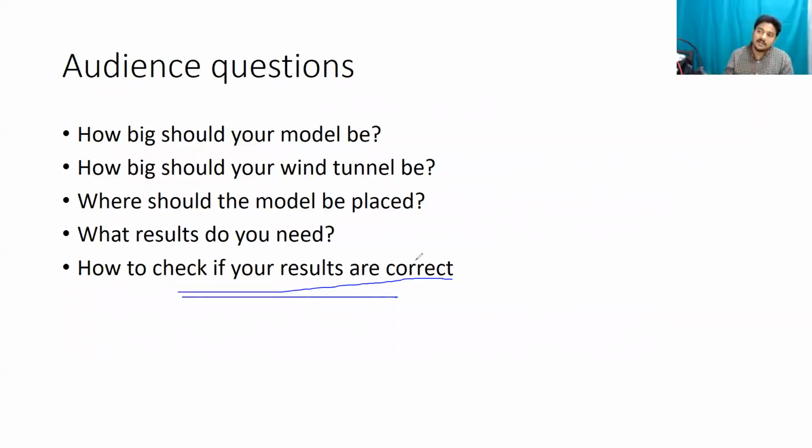I'm glad that you answered it. I'm not picking on you, but that is what many people tell me. Just because convergence is reached doesn't mean that your answers are right. It just means that you are getting a solution. It is not the solution. To get the solution, as Rupak and Jennifer have pointed out, you need to go through the process of validation.